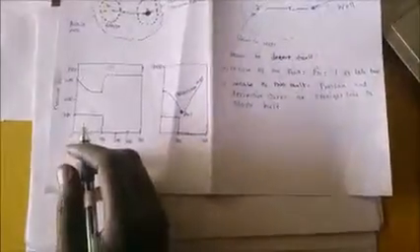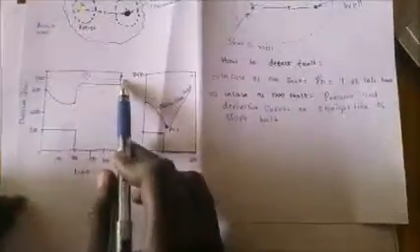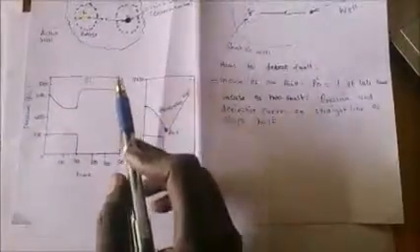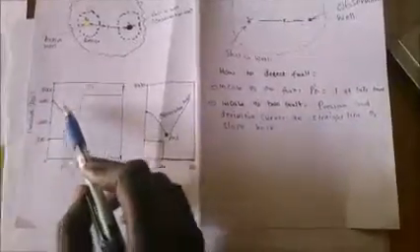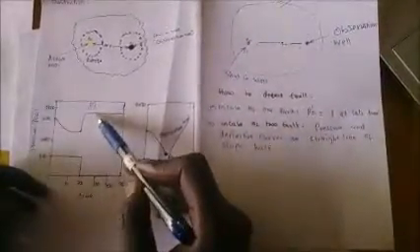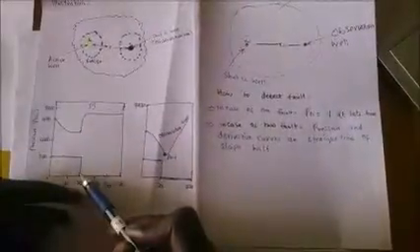So as you can see from the graph, we have pressure here. That's our initial pressure. As you can see, it is from 5,000. And you can see here, there is a production here, and then it is stopped, and then the pressure starts to build up. That's what we call pressure build up. And here we are producing at a constant rate.